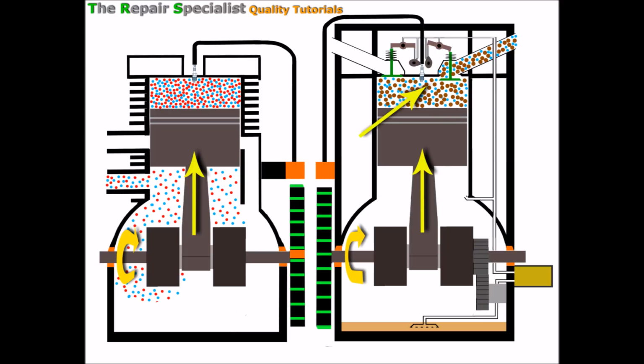of the last combustion. So all of those exhaust fumes going out through the exhaust valve there, because the exhaust valve's open a little bit more now to allow all of that to be flushed out via the exhaust and into the environment. And if we just quickly note that the inlet valve is shut now, so that there's no chance that any of these exhaust fumes can go back through the inlet and towards the carburettor.